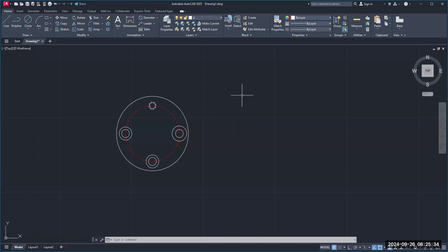But what I want you to do now is I want to come over here to the right side of this. And I want you to type in, or you can go on the menu here, select line right here. And I want you to click a line, start an arbitrary point, click about right here and come straight. Now, look, I anchored that line, just like we've had some experience with that. But if I want this to be perfectly horizontal or perfectly vertical, hit the F8 button on your keyboard.